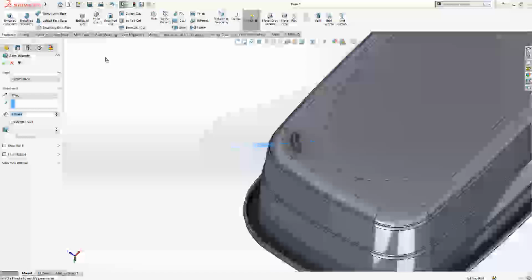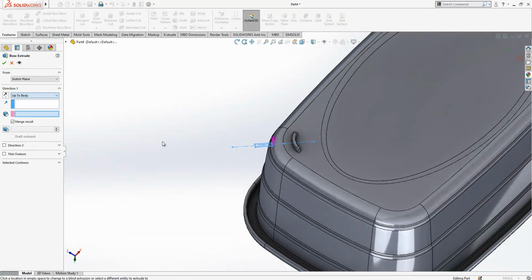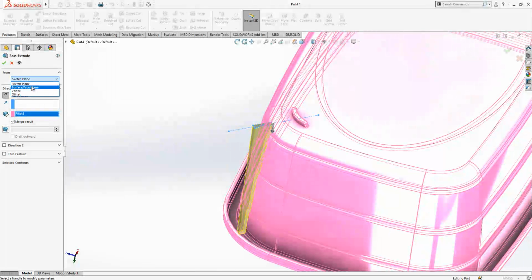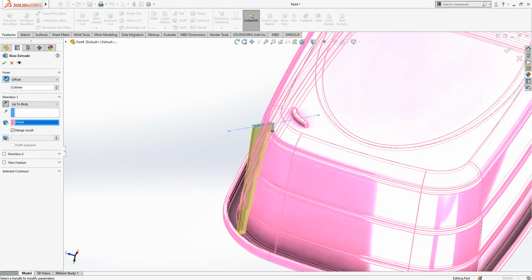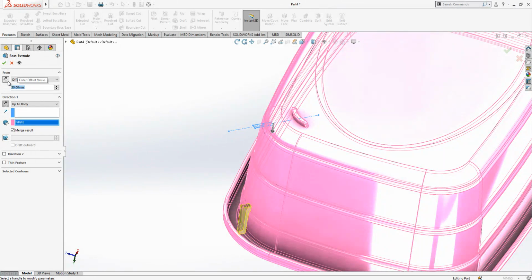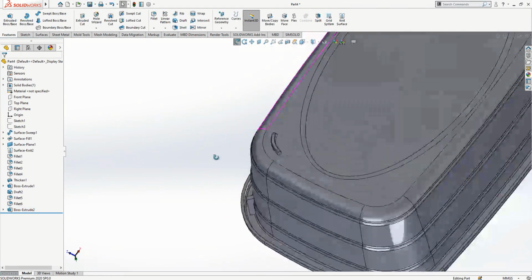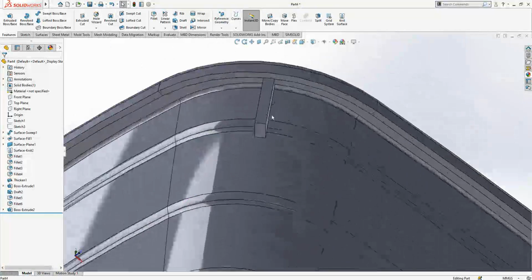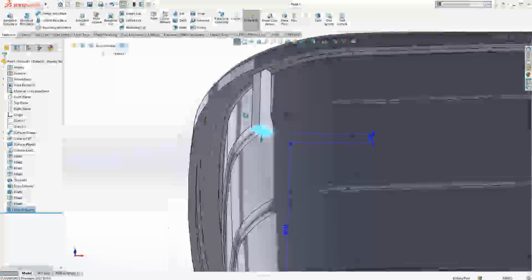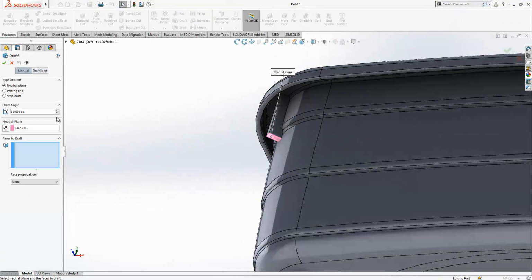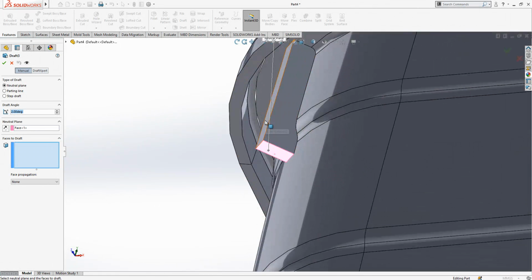And I go to extrude, to body, it will create something like this, and sketch plane offset, reverse offset, 30. Yes, that's good. And I want to give some draft. I select the surface. I will make everywhere 2-degree draft.